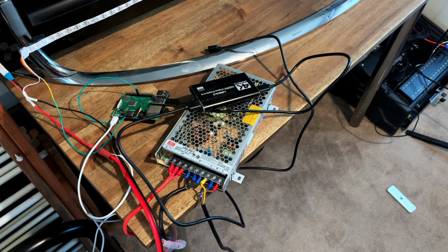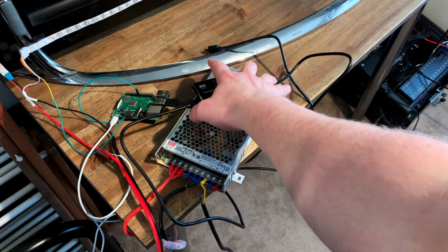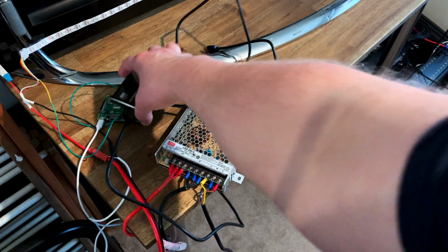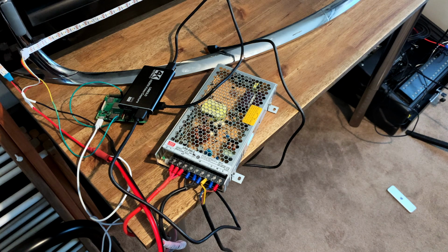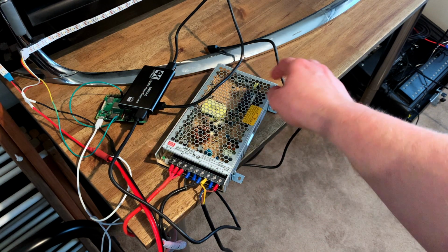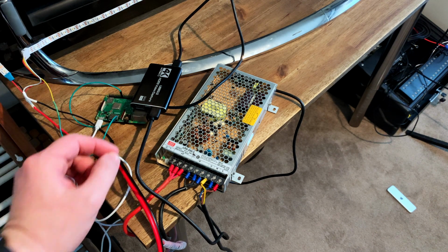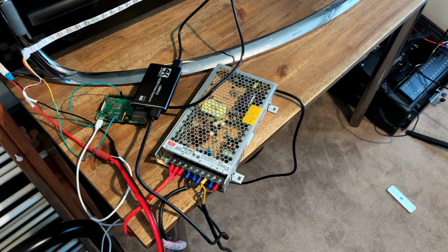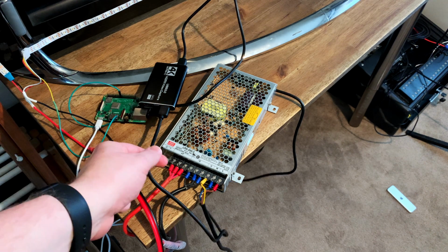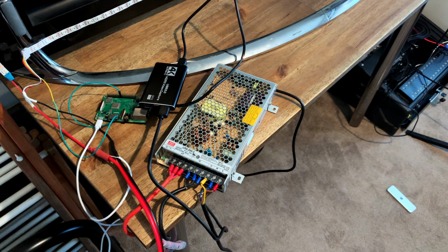Now something that we should bear in mind here is that because we are using the HDMI capture card rather than any kind of native capture, we're only going to be limited to what we can run on one HDMI lead for the reactive LEDs. Anything playing natively on the TV or through a source that's not running through that capture card is obviously not going to work. If, for example, you happen to have a surround sound receiver that can switch your HDMI signals, that should be able to run through this HDMI capture card on the output of that and then into the input of your TV, and that would solve that problem for you.